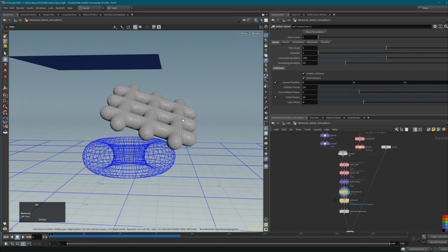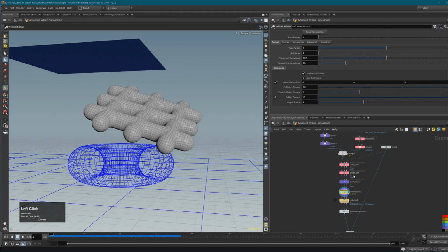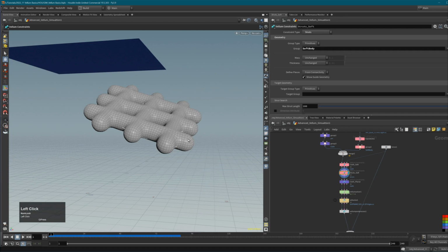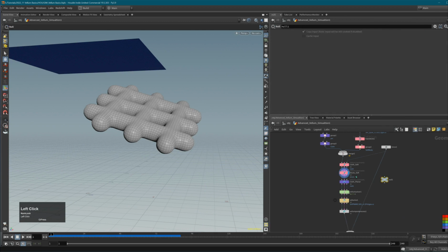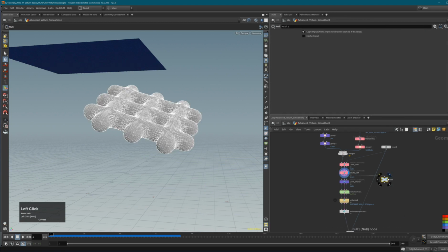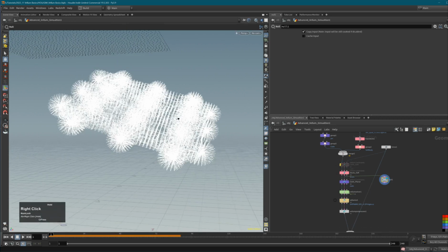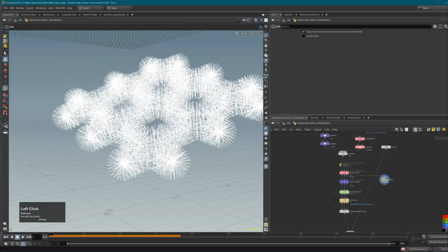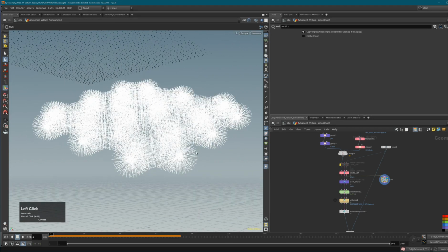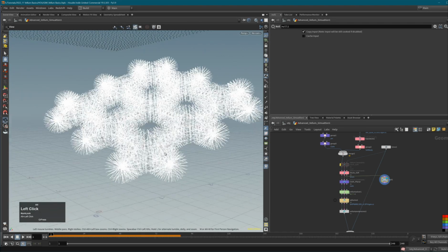Let me show you the soft body, what's actually happening here. We have these strut constraints, I can't say it. So let me apply a pen and null here, again, to just visualize the constraints of these struts. And now I am visualizing both of these constraints because this feeds down here. So I have to disable my cloth constraints to see the strut constraints. And you see the strut constraints are actually volume constraints. So they are crossing the volume of our object and creating these springs inside of our object.